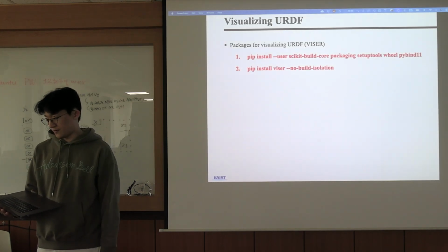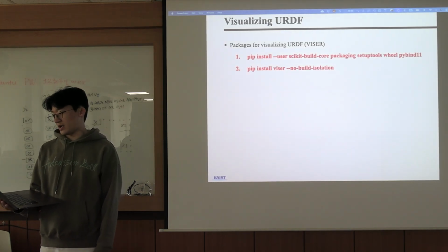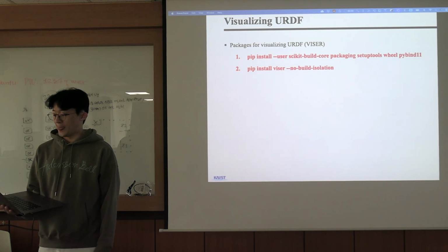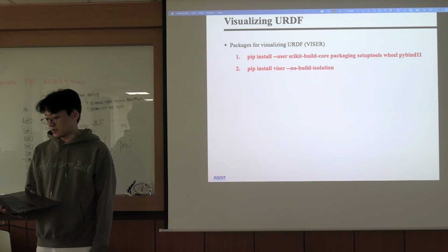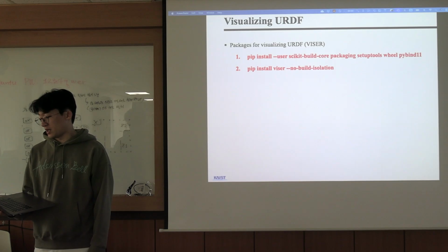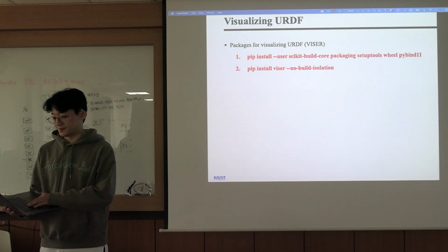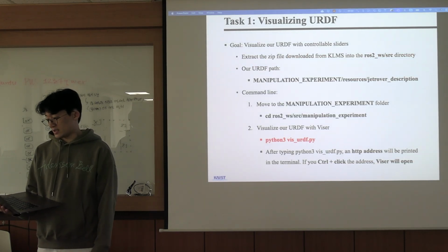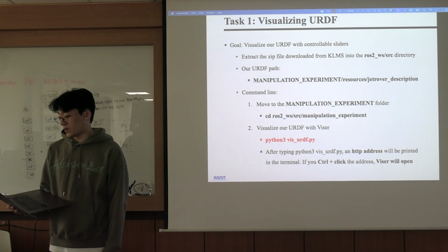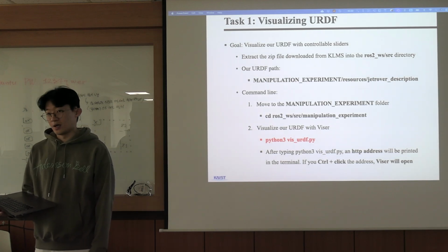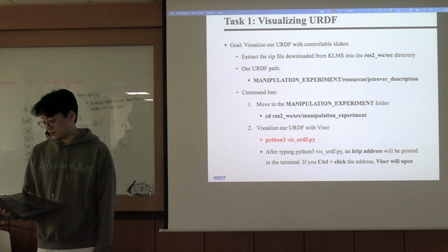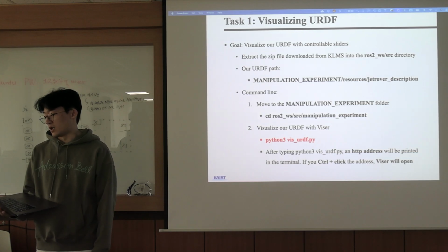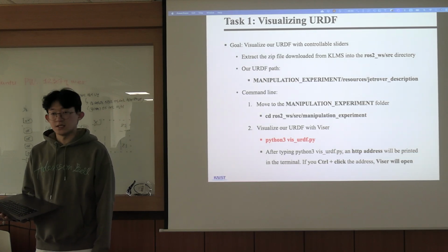To visualize URDF files, we can use a package called Viser. To install it, we first need to set up some build tools using pip, and then we install Viser itself. Today's first task is to visualize our URDF with controllable sliders. To do this, you should first extract the zip files you downloaded from KLMS